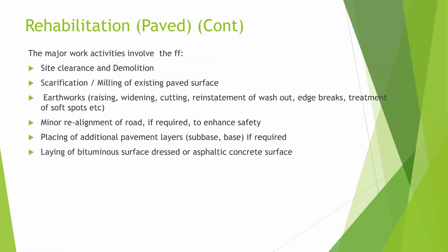Now, the activities involved here are site clearance, scarification and milling. You have earthworks, minor realignment of some sections if required to enhance safety, placing of additional pavement layers, and also the bituminous surface or the asphalt concrete surface, that's the surfacing works.